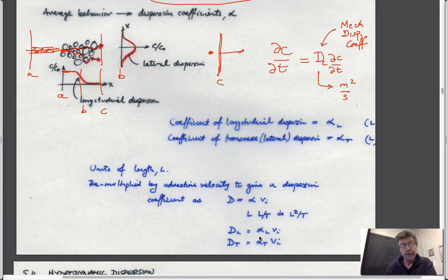And the two parts are a coefficient of longitudinal dispersion. So in other words, we can represent this term D_L as being the product of two other terms. A coefficient which we define as a function of an aquifer, and a coefficient that we define as a function of the advective velocity in the longitudinal direction.